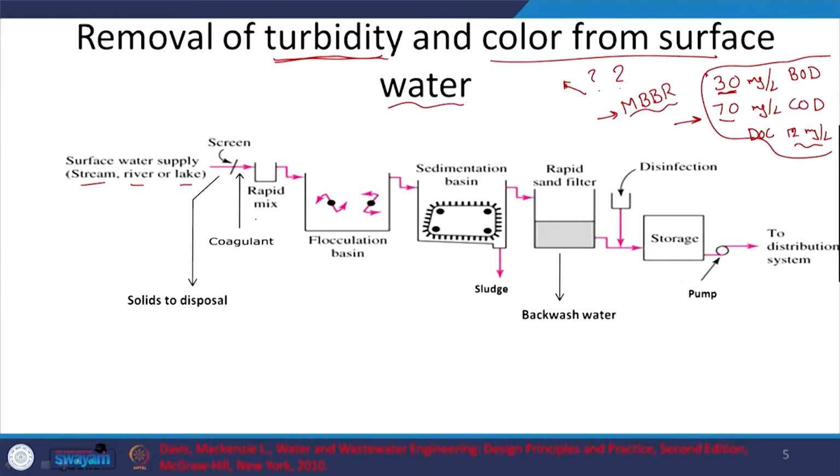Yes, we will look at why a coagulant is required later. For mixing it well and for coalescing the particles so that the initial coalescence starts, you are going to have rapid mixing, and then you will have a flocculation basin where you want to form the flocs. So here the turbulence and thus the mixing intensity will be less.